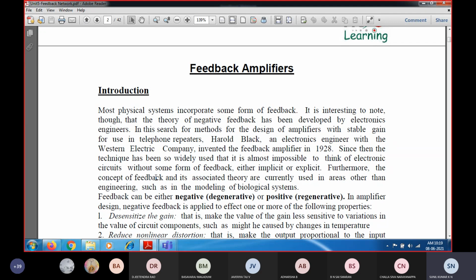We make the circuit elements in such a way that however much the amplifier gain is going to increase, at the same time the feedback network is going to reduce it. That is the configuration we keep in the oscillator, and because of that you get a sustained oscillation.